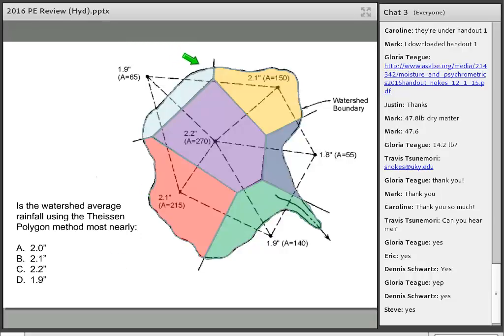So you do a 2-inch contour that would come in somewhere about midway here between the 2.1 and 1.9, and come down here somewhere because it's about a third of the way between the 1.9 and the 2.2, and then halfway between the 2.1 and come out. And you just essentially build those contour lines, measure the areas around them, and sum them up again. It's a bit more complicated because every time it rains, that method's going to change.